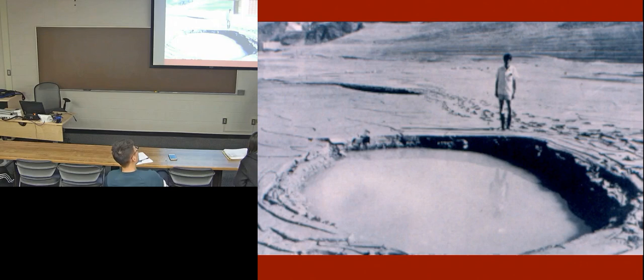Well, they weren't unexpected because we knew that the riverbed was very porous and it could easily collapse at various places, but never anybody expected 500 of them. But you can see that even during the partial filling of the reservoir, the silty material formed a cake on the top of the basic riverbed material.